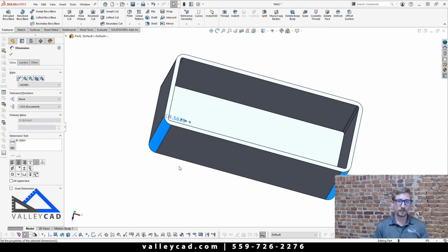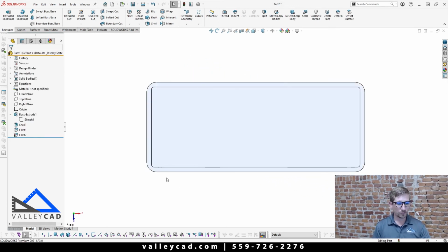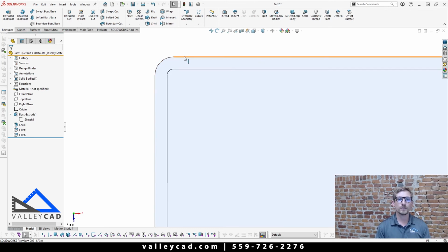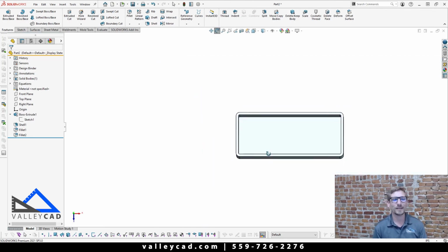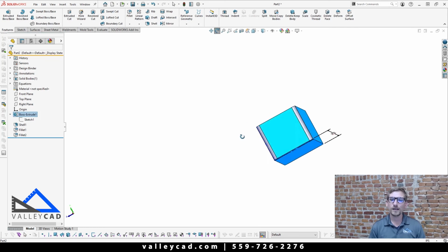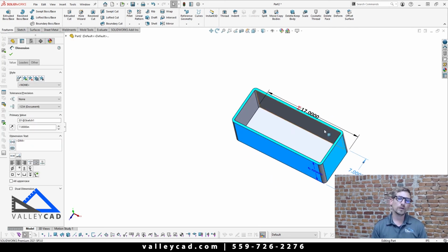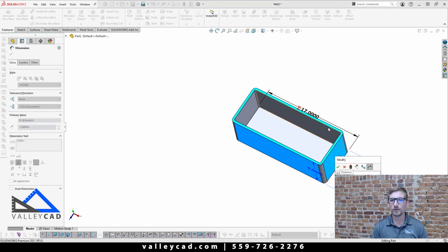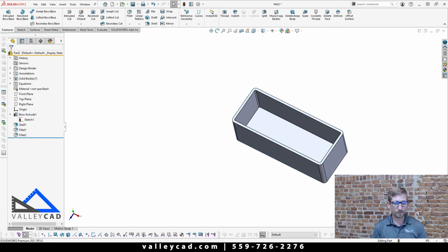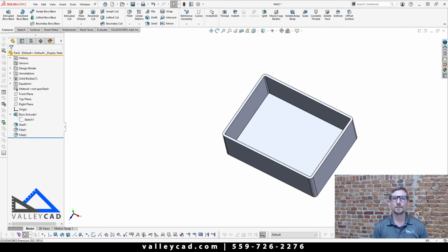You'll see that this now is 0.5625. Do a Control Q to rebuild it. And now you'll see that my value is automatically updated. So that way my fillets here look consistent as well. All right, so now let's come in for our last one. Let's say I want to make it to where this 7 always equals 3/4 of that value there. So I'll say that this here equals this times 0.75. Say okay to that. So it's going to equal 12.75. Watch this, Control Q, updated.